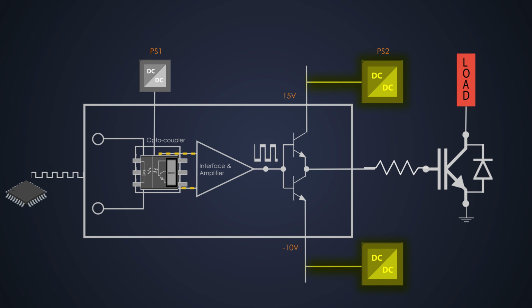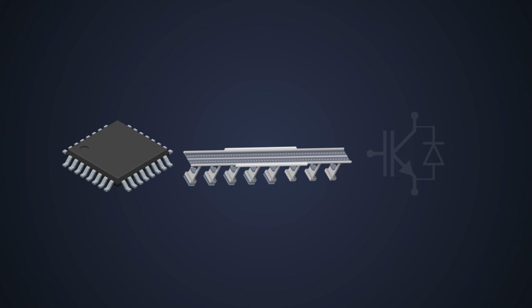But we can't directly use this solution. We are dealing with very high power here. So safety is the biggest concern. Well, we need to add some safety circuitry like short circuit protection, undervoltage protection, overcurrent protection, and transient protection at the gate. This protection circuit is very crucial at the driver circuit because in the end, it is the bridge between high power and the control circuit in the system. If anything goes wrong, the repercussions will be very dangerous.